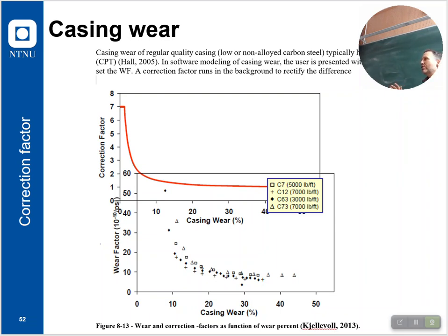It doesn't change through the operation. You set wear factor, say 5, in your equation, and you need it to be something else early and something else later. Basically, standard steel has what is called a contact pressure threshold. You come to a certain pressure and there will be no more wear. It just stops. It's a number.